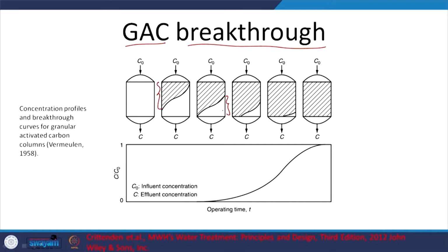So, what is happening? I guess we did discuss this. So, here this part of the adsorbent, there are no more sites available for adsorption, and now I guess the active mass transfer zone is out here. So, this profile has some relevance, we will look at that. For example, this is the breakthrough, and this particular graph corresponds to the profile that we see out here.